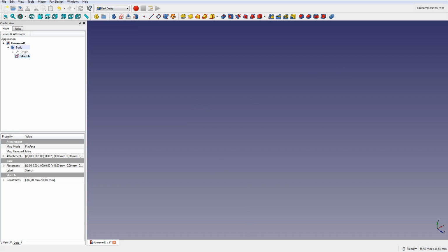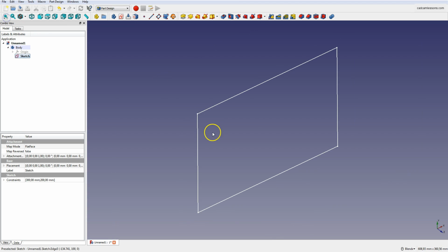We use this rectangle to create a solid. However, there are a few things that can help us navigate. Our sketch is not visible in the work area. We can use the mouse wheel to zoom in or zoom out, but this will not give us confidence that we will find the sketch. An easier way is to use the button Fit the whole content of the screen. OK. But the geometries are shown in a rather strange position, and it would be much more convenient to work if we were looking at the 2D geometry in the top view. There is an easy way to do this. Just select the option Set to Top View.